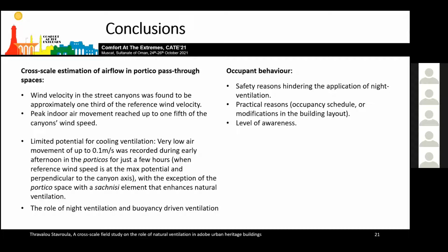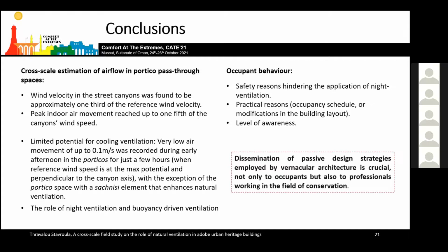Yet in other cases, occupants seem to ignore an apt window operation pattern or are unable to apply such due to practical reasons, for example, their occupancy schedule, safety, difficulty in accessing the upper windows. Alterations in the building layout, the arrangement of the windows, and the role of the courtyard are also reasons for halting the potential of natural ventilation. Consequently, the dissemination of passive design strategies employed by vernacular architecture is crucial not only to occupants, but also to professionals working in the field of conservation.